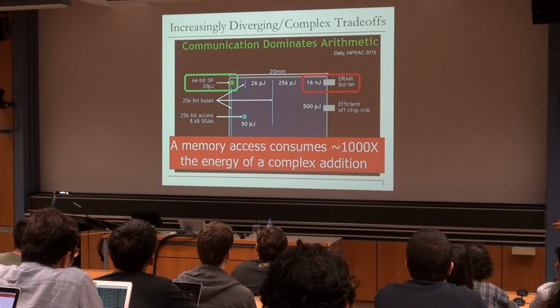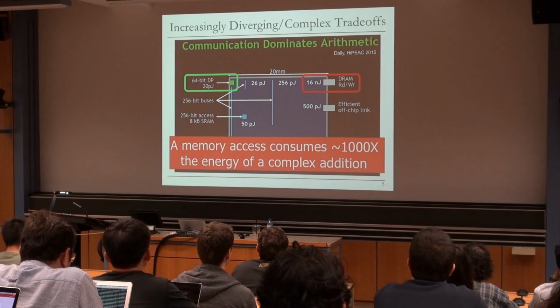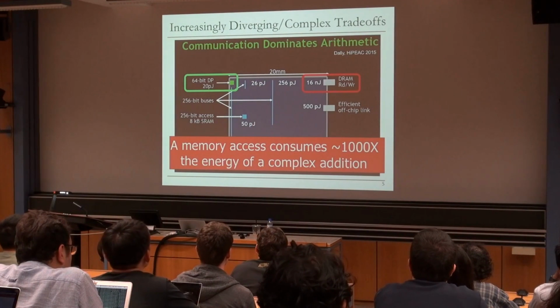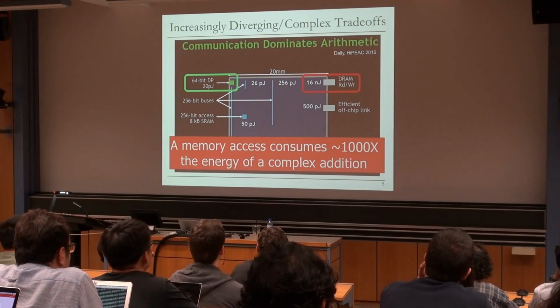Now, it's good to ask the question, are we doing things right in a principled way if we're actually bringing all of the data into the processor to process it? Because let's assume that you're doing a floating point addition. You need 2 source numbers. Let's assume that they're in different parts of DRAM. You do 2 DRAM accesses to bring the 2 floating point values into the registers. You do the double precision floating point addition, and you do 1 more DRAM access to write the result back into DRAM. That's 3 DRAM accesses for a single simple operation. And assuming that you have a lot of random accesses to data, which you may actually have in real applications, because a lot of the real applications don't have very good locality, as a result, you're wasting a lot of energy just moving data into the processor to do the operation.